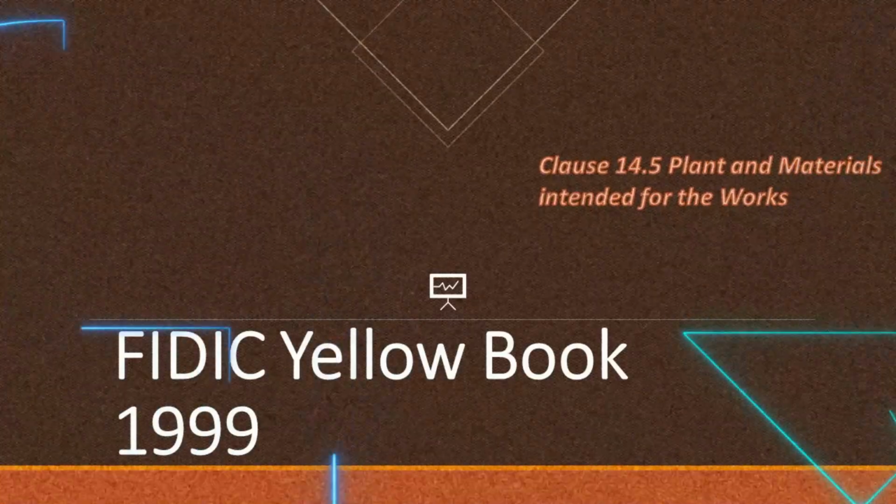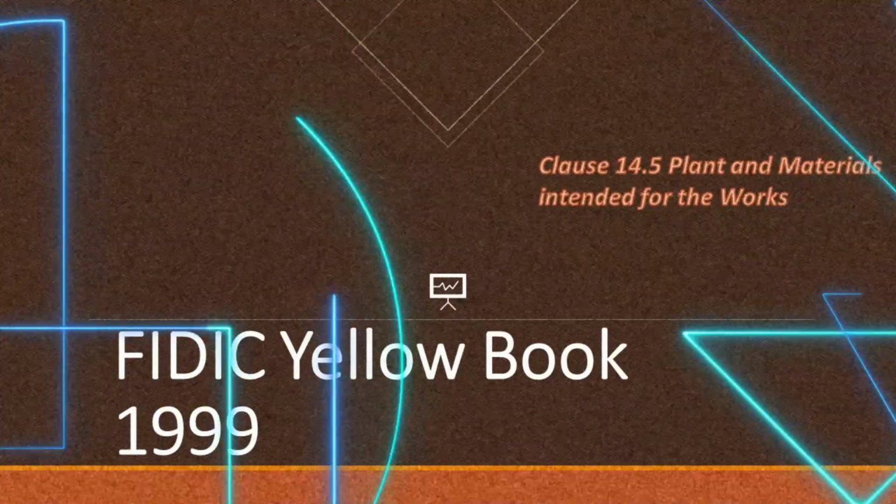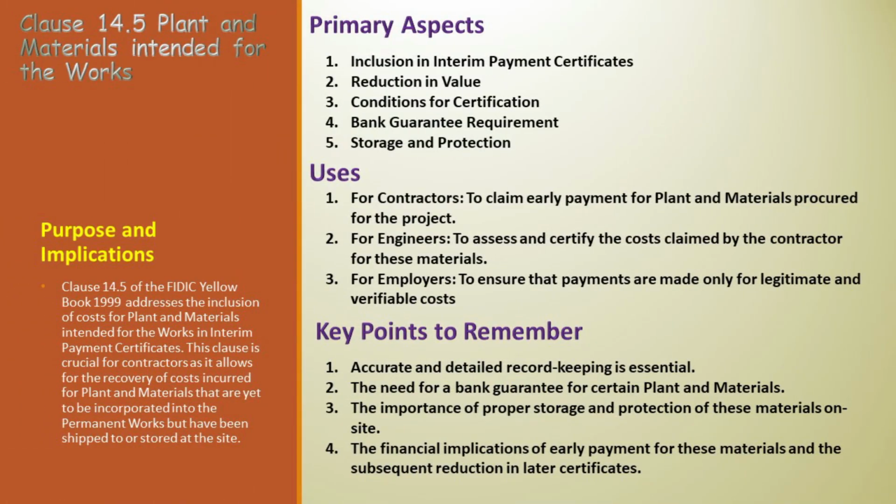Now, let's dive into the world of FIDIC Clause 14.5 and unlock the secrets it holds. Purpose and implications. The essence of Clause 14.5 lies in its provision for contractors to recover costs for plant and materials that, although essential to the project, have not yet been incorporated into the permanent works. This clause assures financial compensation for materials that are either in transit or stored at the site, but not yet part of the permanent works.